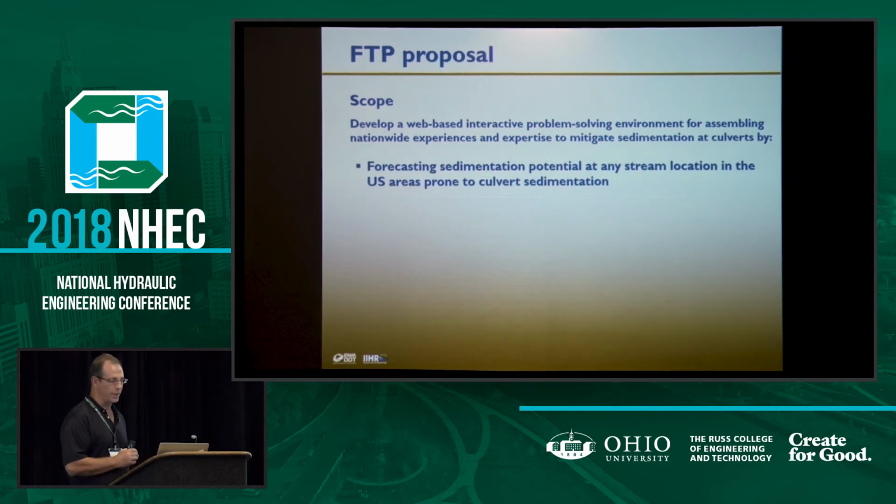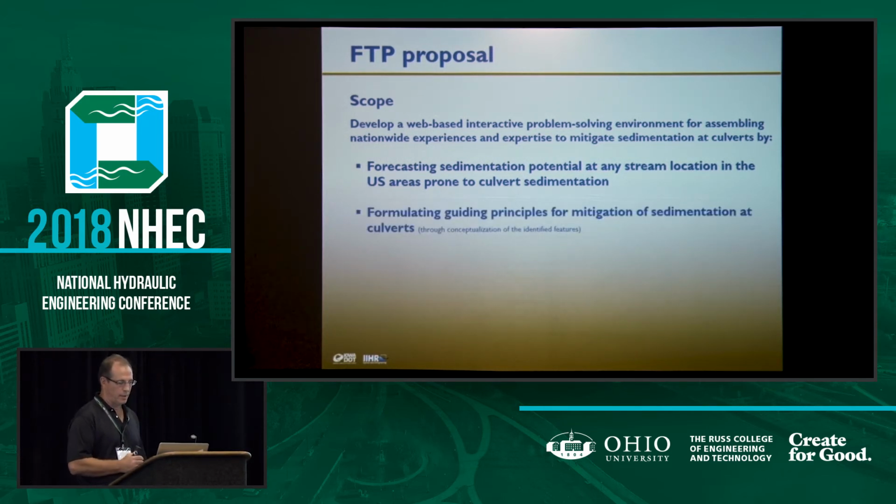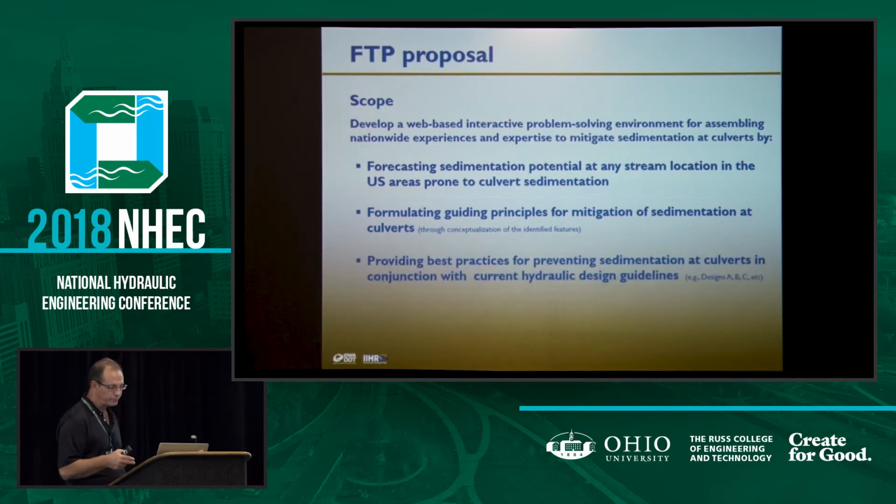So again, just in summary, the tool we've created is a forecasting tool, so it's a design aid. And we've created some guidance for mitigating sedimentation in culverts, multi-barrel culverts with the wedges. We'd like to get more examples or sites where we can look at both the end wall and the weir, downstream weir, to see how effective they can be more nationwide instead of just 2 or 3 sites in Iowa.